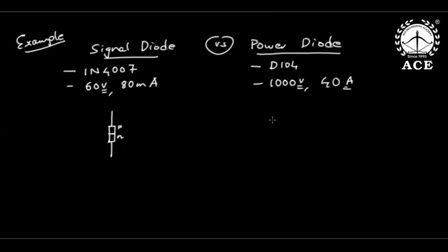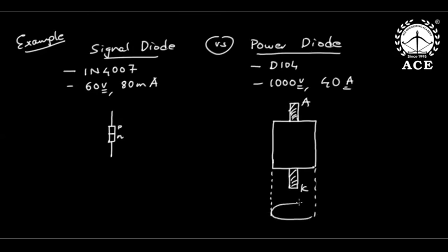That is why this power diode's cross section area will be very, very large. That is the first thing. And if you want to withstand more voltage, insulation level. Here this is metal terminal 1, this is metal terminal 2, of course we call them anode and cathode. So what happened first? I increase the cross-sectional area of the semiconductor material.